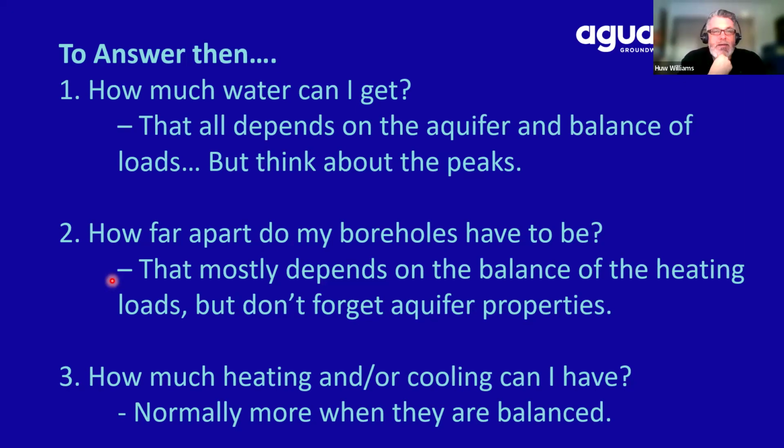How far apart do my boreholes have to be? Well, I think that we probably showed that quite nicely: it depends on the balance of the heating and cooling loads, but also, of course, as was demonstrated, you can't forget the aquifer properties about how far apart your boreholes have to be. How much heating and cooling can I have? Well, normally more if they're balanced. The more balanced you can get them, the more heating and cooling you can get; the more imbalanced, you probably have a higher risk of unacceptable thermal interference.